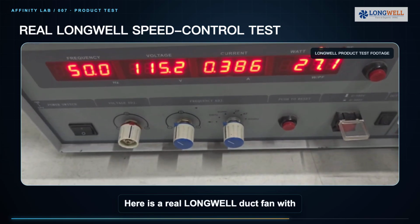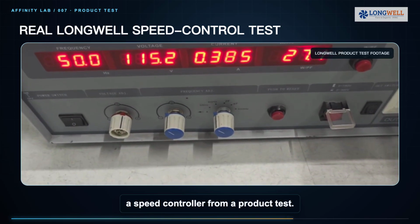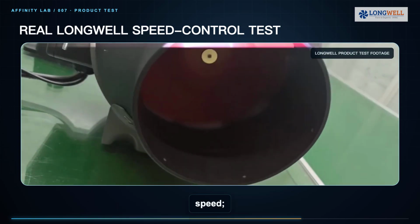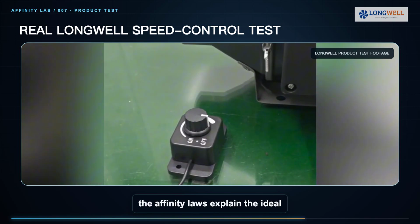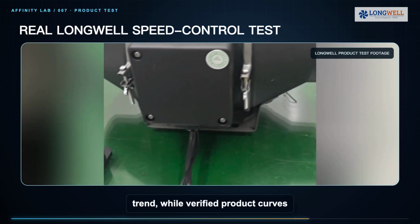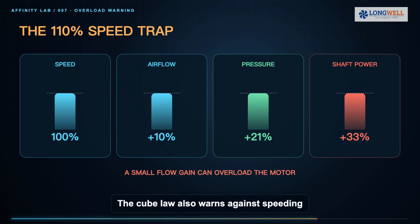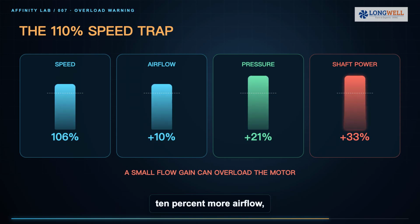Here is a real Longwell duct fan with a speed controller from a product test. The controller changes the operating speed, the affinity laws explain the ideal trend, while verified product curves and measurements confirm the actual result. The cube law also warns against speeding up. A 10% speed increase predicts 10% more airflow, 21% more pressure, and roughly 33% more shaft power. That can overload the motor even when the airflow increase looks small.